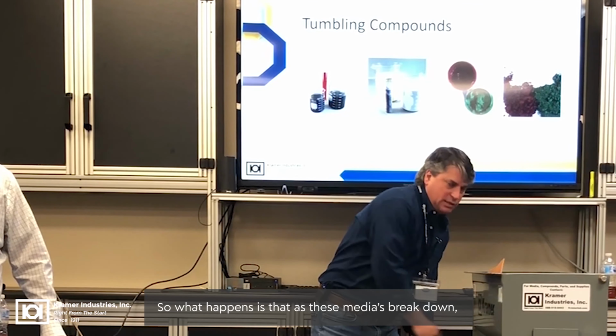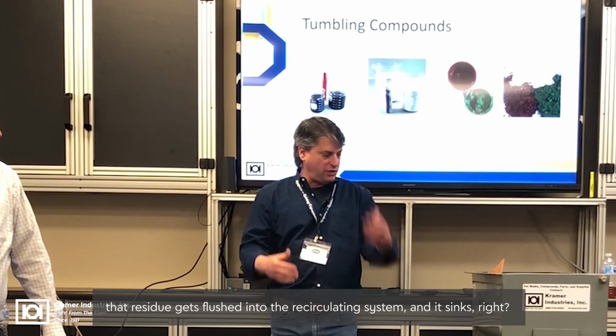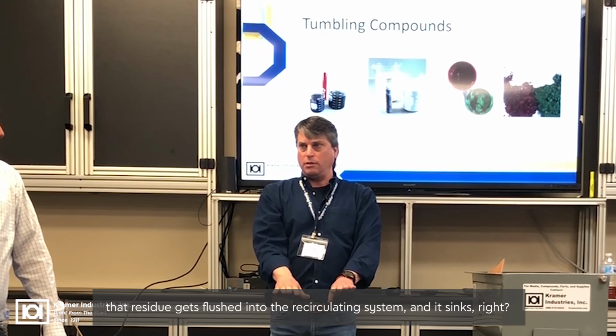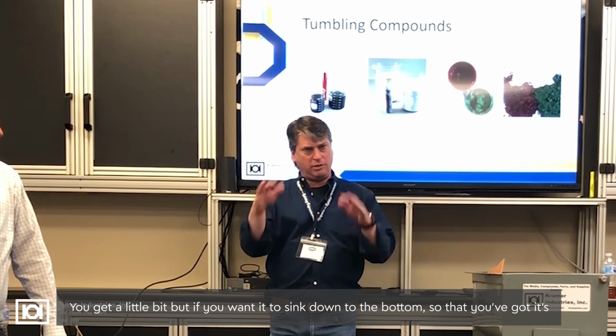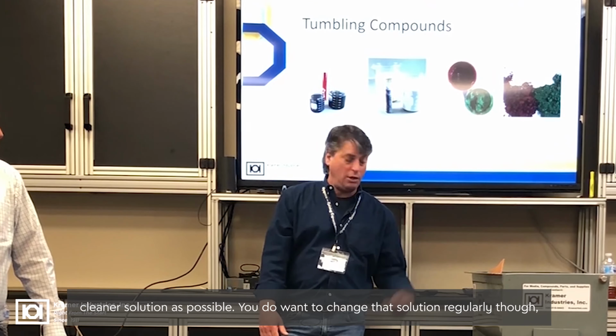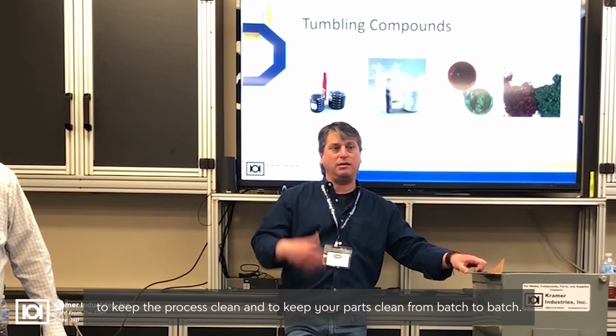So what happens is that as these medias break down, that residue gets flushed into the recirculating system and it sinks. And so you don't want to necessarily recirculate the residue. You get a little bit, but you want it to sink down to the bottom so that you've got as clean a solution as possible. You do want to change that solution regularly though to keep the process clean and to keep your parts clean